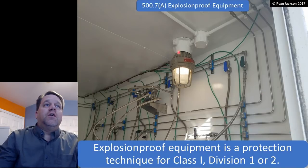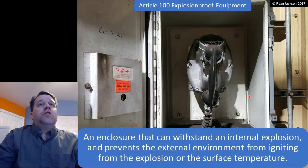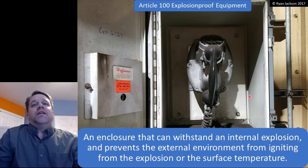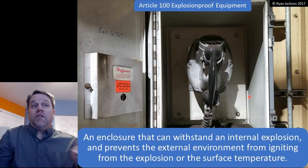This luminaire here is an explosion-proof luminaire. Explosion-proof equipment is defined in Article 100 as an enclosure that can withstand an internal explosion and prevents the external environment from igniting from the explosion or the surface temperature.